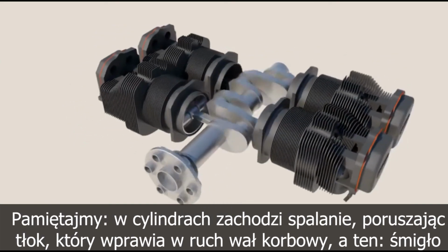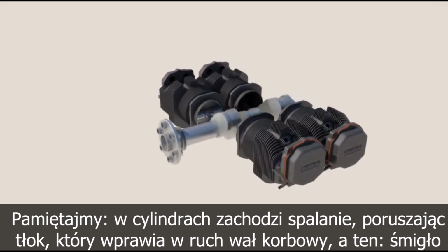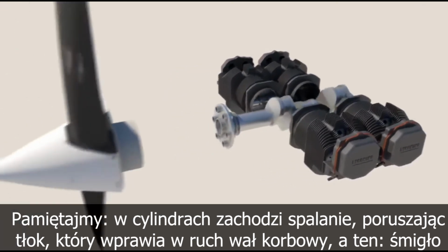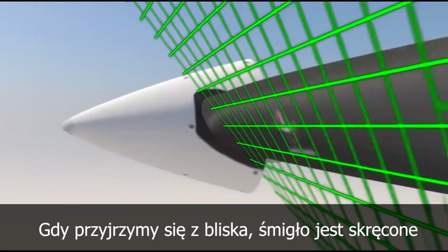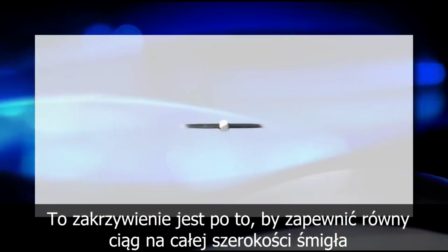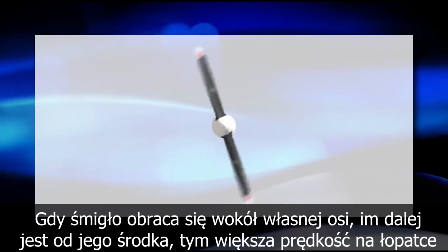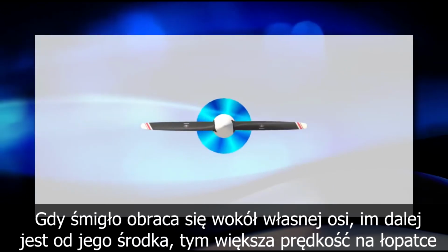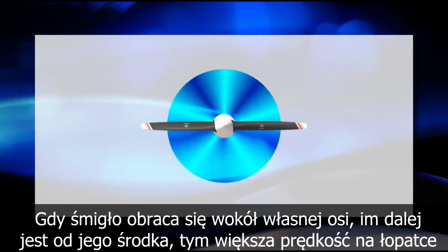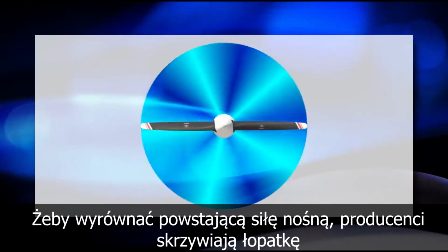Remember that as the combustion occurs in the cylinder, the pistons rotate the crankshaft, which directly drives the propeller. The propeller, when closely examined, is actually twisted. This is simply to create equal thrust along the propeller blade. Since the propeller rotates around its hub or center, the further the propeller extends out of that hub, the faster it spins. To create equal force throughout, manufacturers twist the blade.